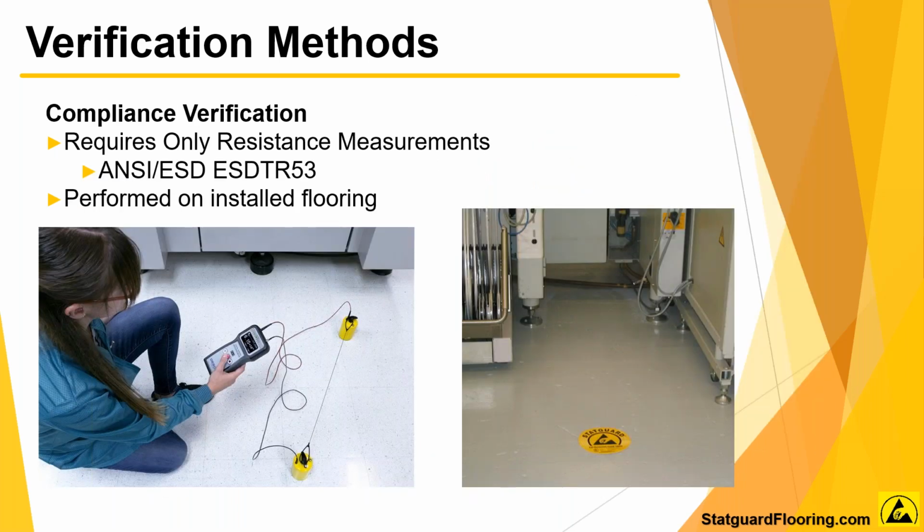The surface resistance meter is referenced and designed to be used to make measurements in accordance with the test procedures and compliance verification ESD TR53 resistance measurements. The compliance verification is an ongoing test to confirm the floor is meeting the required specification. Plans shall document the test methods and equipment used for process monitoring and measurements. The test equipment selected shall be capable of making the measurements defined in the compliance verification plan of the S20.20, section 7.3.